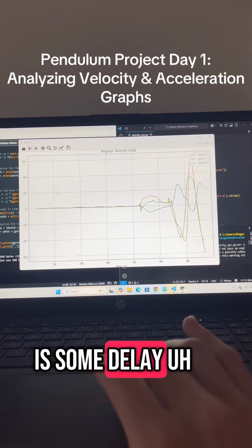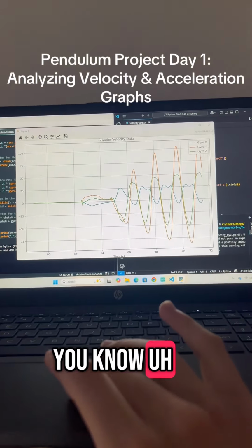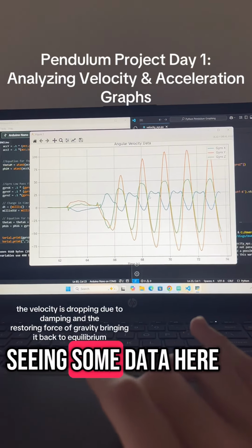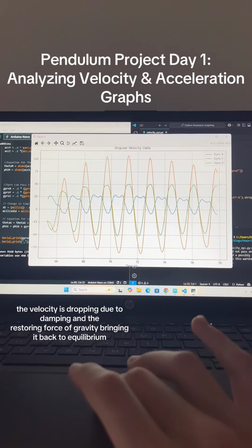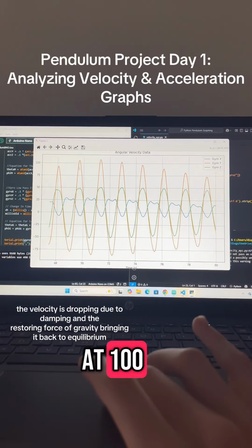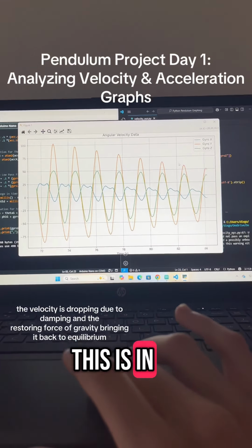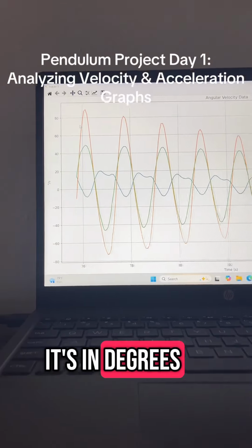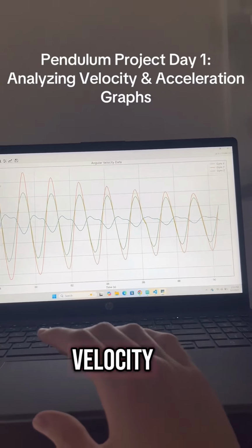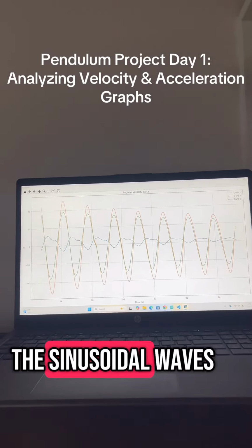There is some delay because we are using USB, but we are seeing some data here. So now it's increasing. So you can see how the velocity is at 100. Now it's dropping down to like 75. So here you can see that it's in degrees per second because it's rotational velocity, it's angular velocity, it's not meters per second. You can see the sinusoidal waves.